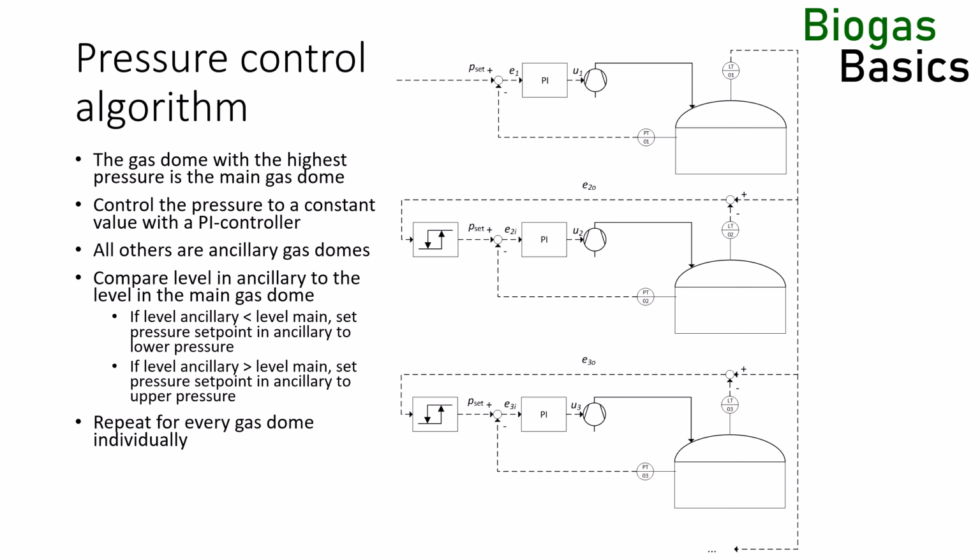Biogas will be stored or unloaded slowly and equally among all gas domes, and the volume flows, and thus pressure gradients between the tanks are minimized. The gas consumers are also better controlled by the gas dome level, as low-level or low-pressure events in individual tanks that could trigger the release of the gas safety chain are avoided.